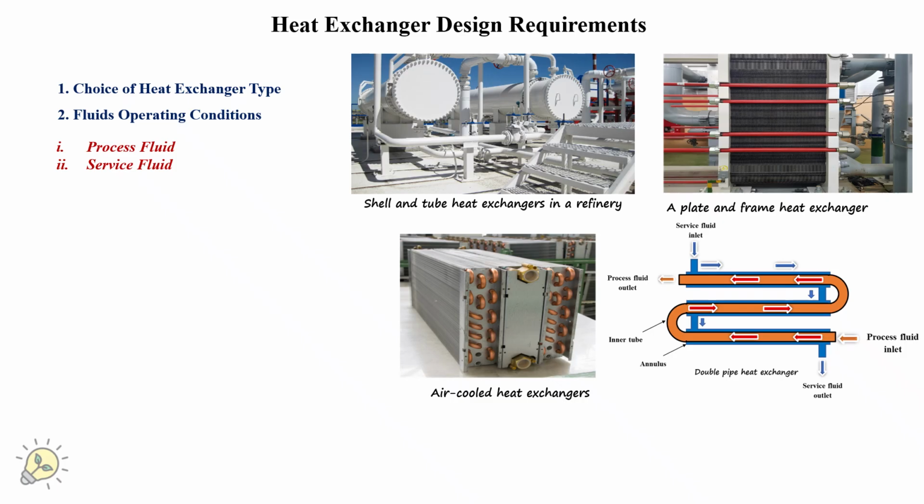This external equipment could be a boiler which provides hot water or steam, or it could be a cooling tower or chiller to provide chilled water for cooling purposes. These can be specified by the entering and leaving temperatures and the mass flow rate of the circulated fluid.